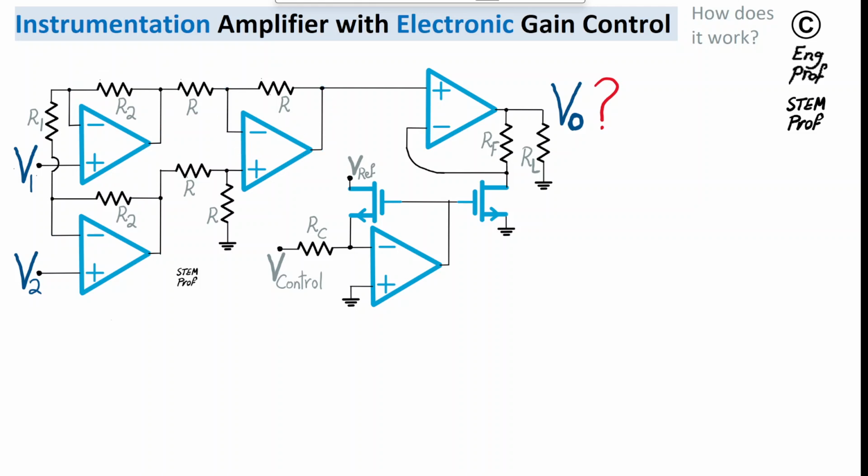So with that in mind, I can say all the op-amps in this circuit are operating in linear region, and therefore I can assume that the virtual short is valid for all op-amps here, which indicates that the voltage at the positive input terminal is equal to the voltage at the negative input terminal, or basically what we refer to as virtual short for the op-amp, holds.